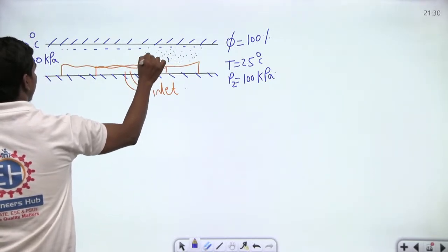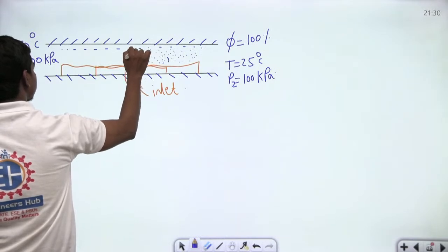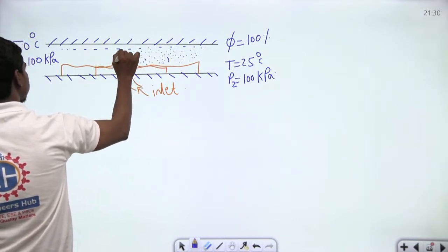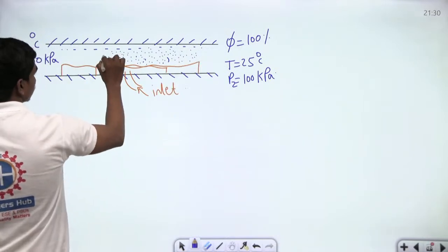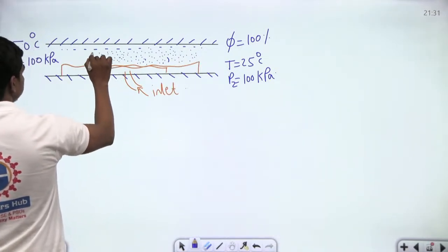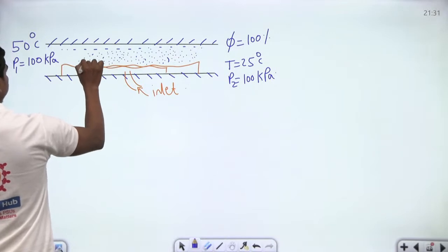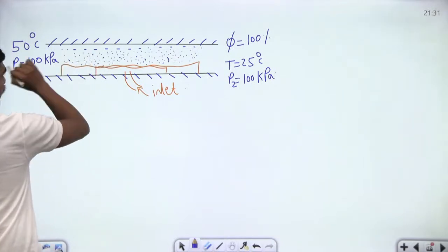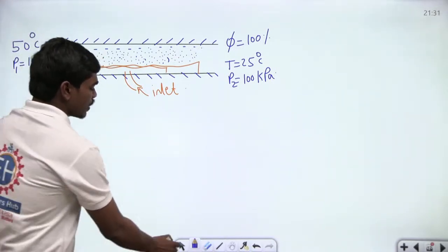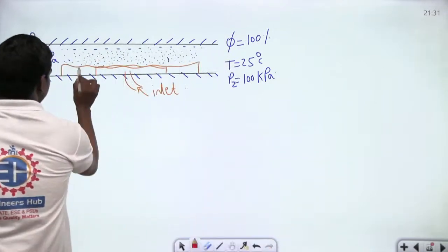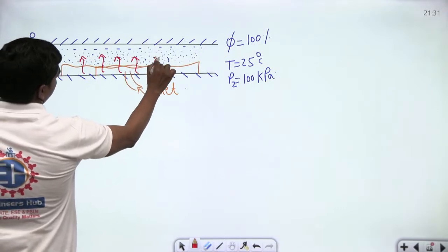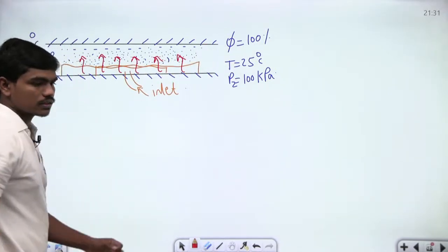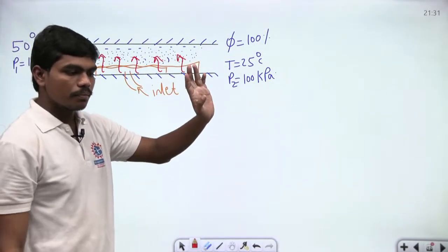What do these air molecules do? They take some water vapor along with them, and this adiabatic saturator is of finite length, such that the air gets saturated by the end. Some water leaves from the water to the air throughout the path.